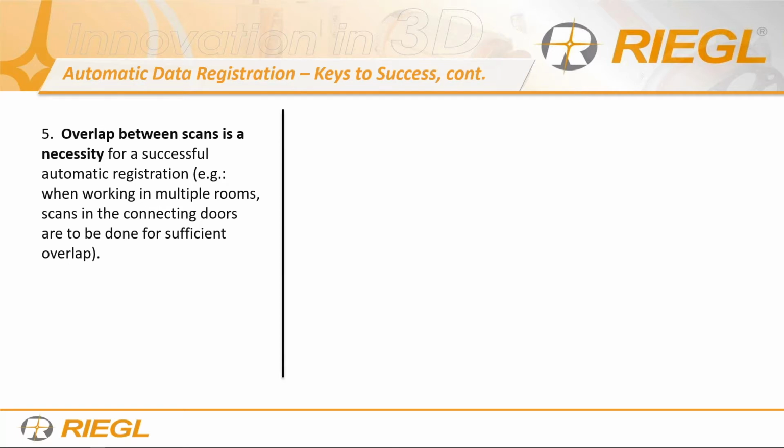where we need any kind of targets out there to register one position to another, right? We analyze the data, compute the planes of voxels so that it can then find the matching plane. So we don't make use of any targets for registration. Now we make use of the targets to tie it down to survey control.